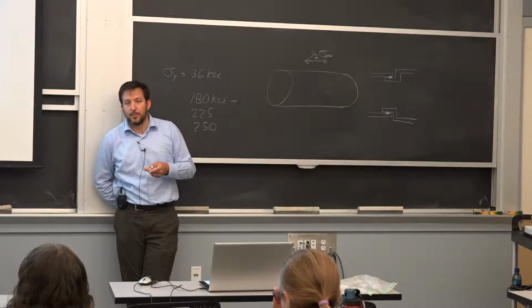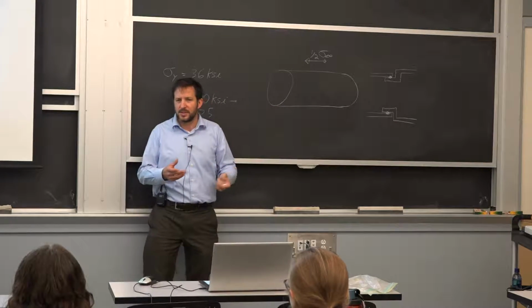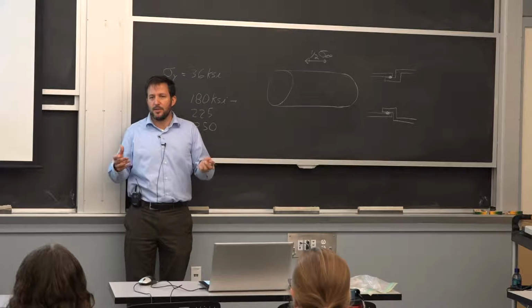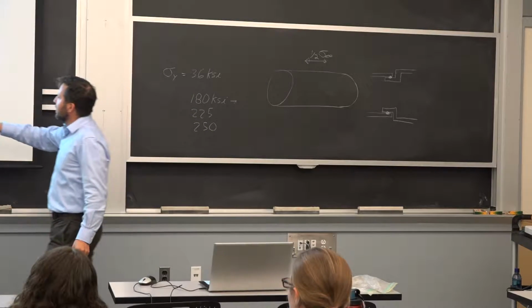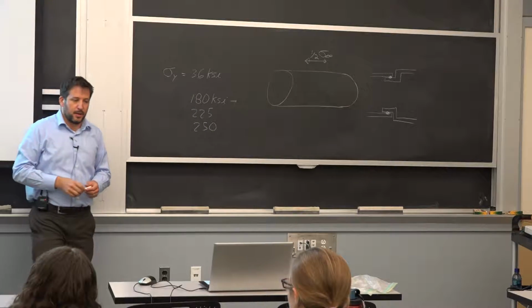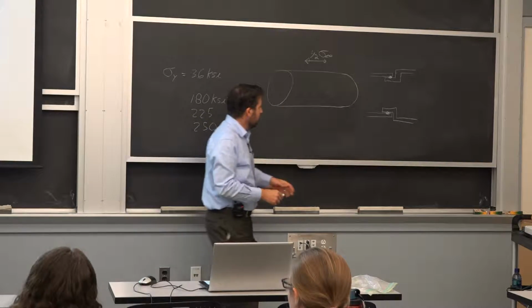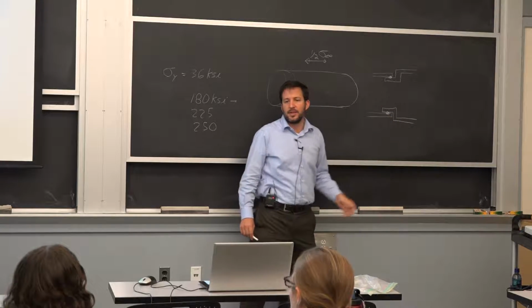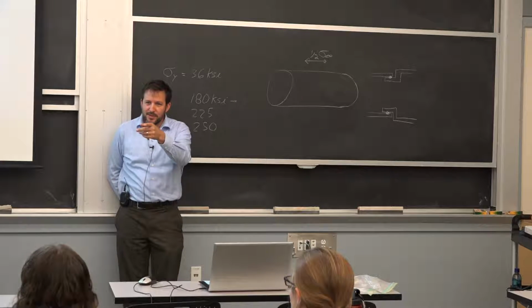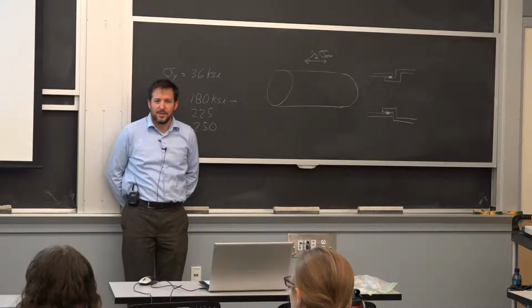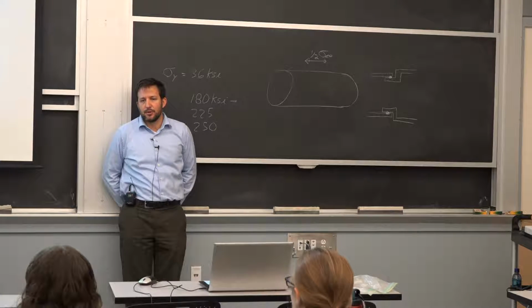The reason you put a clamp is if one moves, you don't want it to disengage as opposed to the other. So you want some flexibility, but in reality, you don't want these things to go very far. So I'm showing a clamp here, and that's actually what caused the MWRA break. A big steel clamp was connecting those two pieces together on the outside. What exactly happened is what you said. There's bending between the two cylinders, not so much from the original installation, but from settlement in the ground.